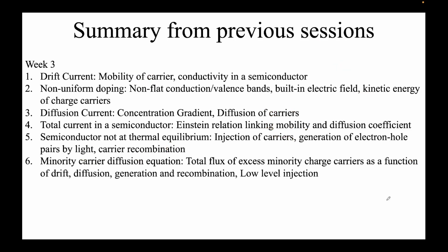And this is from the last session, where we talked about the drift current: if you apply an electric field, or in the presence of an electric field, how the carriers move. So we saw that Vd, the drift velocity, equals mu, the mobility, times the electric field E. And we also saw how conductivity is related. So we saw that n is the concentration, e is the electronic charge, plus p e mu p. p is your holes, obviously, and n is your electron concentration.